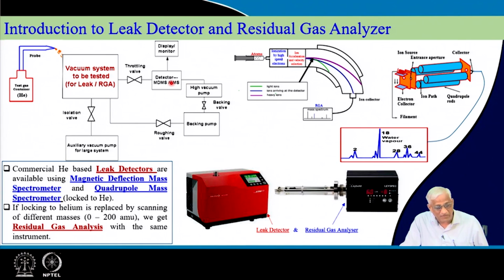From 10^-2 to 10^-5 torr, if a throttle valve is there, it can naturally withstand a high pressure drop, and a signature of this gas chemically can be felt when this valve is opened. The proportionality constants can be adjusted in the calibration constants. This has to be done. How do we do it? You can put a standard leak here and calibrate it, and then use this. Under these conditions of volume, how the standard leaks will work, because the gas gets distributed and leaks using that equilibrium pressure, all that is a big field by itself.